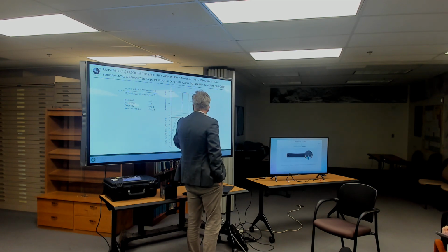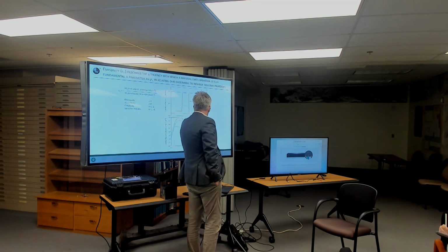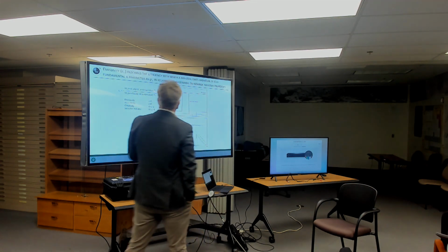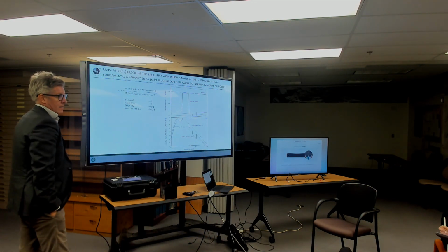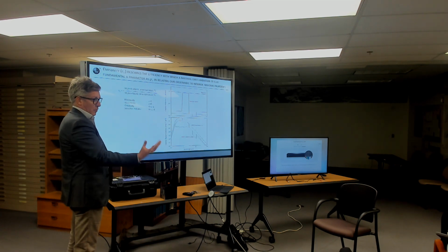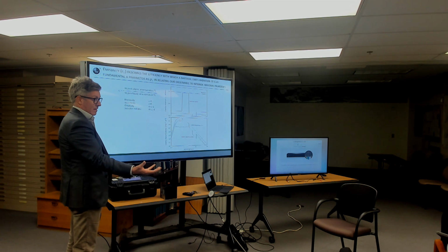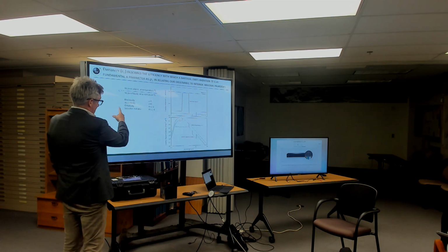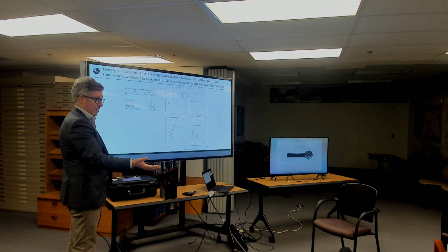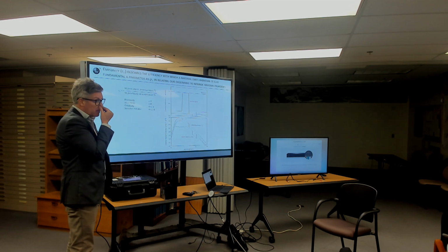And that makes sense because here is the minima in the energy emitted by my selective radiator. Right. So do people just see how you derive emissivity? You take a real world material that you care about and measure the amount of energy it emits at a certain temperature, and then you just compute the black body flux at the same temperature, divide one by the other, and that gives you the spectral emissivity.